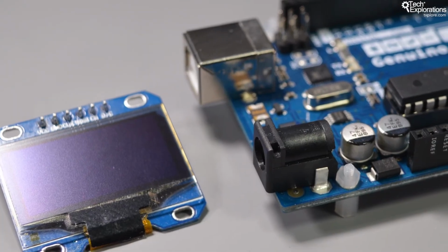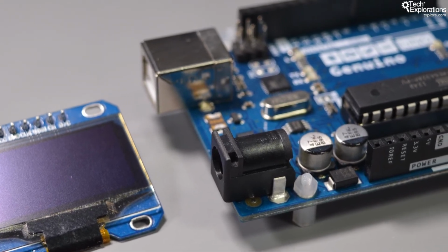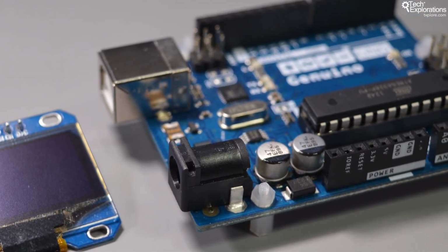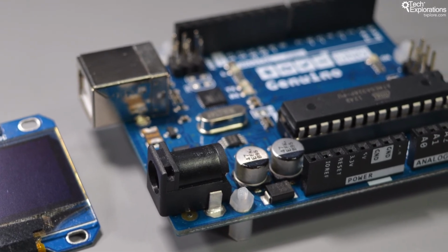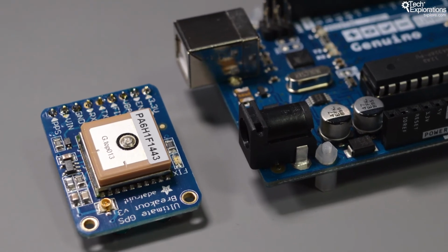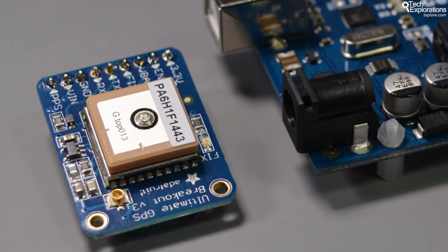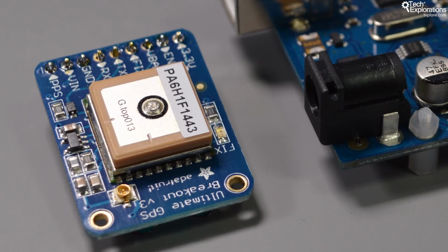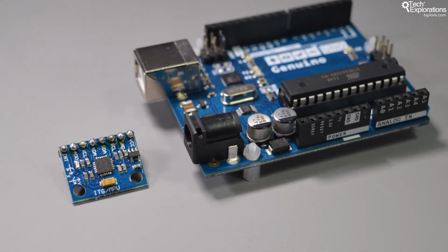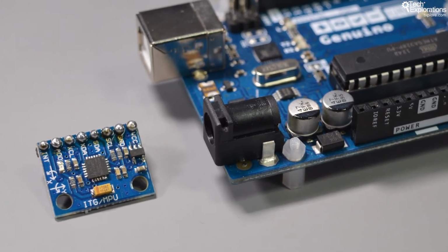In this lecture, I gave you an overview of the 3 communications protocols that you can find on the Arduino that make it very easy to communicate with external devices and peripherals, and even other Arduinos and a computer. So these are the UART serial interface, the I2C interface, and the SPI interface. And the Arduino ships with one of each. If you need to connect additional serial devices to your Arduino, then you can implement additional UART interfaces in software inside a sketch using a library called Software Serial.